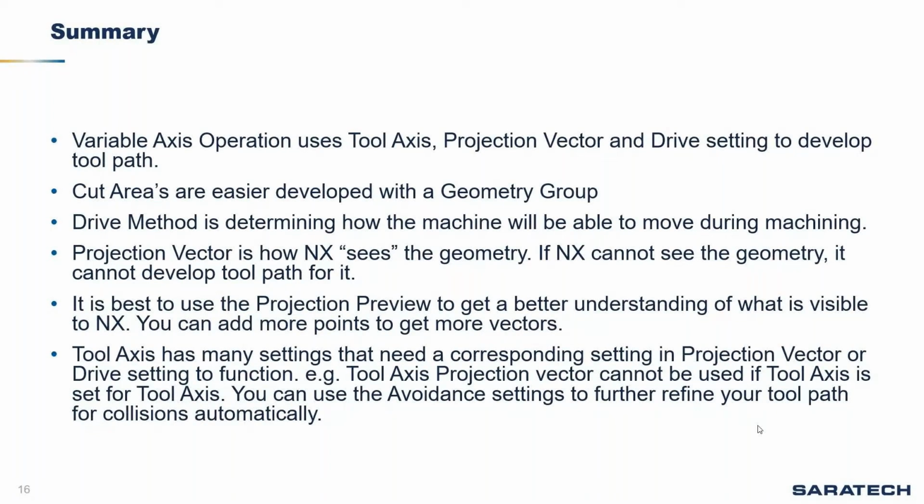It is best to use projection preview to get a better understanding of how the tool is looking at that surface. If you don't see the red arrows going around the surface the way that you expect the toolpath to go, then you're not going to get the toolpath that you want. So before you hit generate on these toolpaths, you want to make sure that your projection preview is giving you the projection vectors that you desire, so that you don't generate in vain. Previously, we had to generate in vain and just keep trying options. The projection preview stops all that from happening.